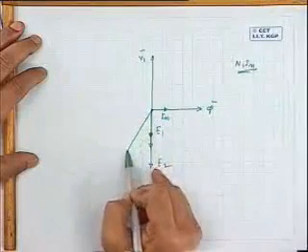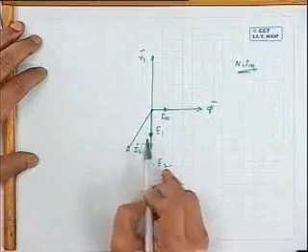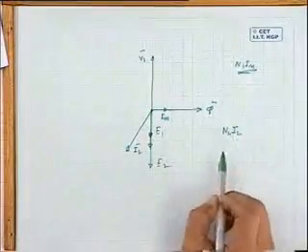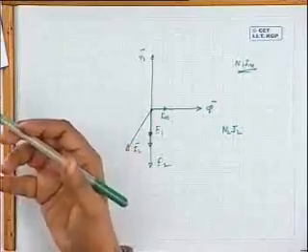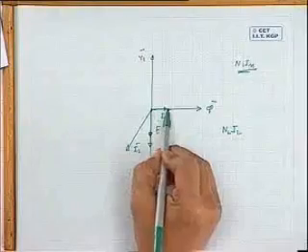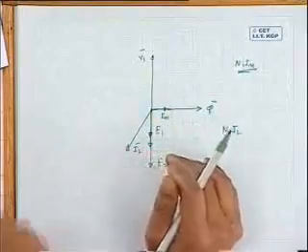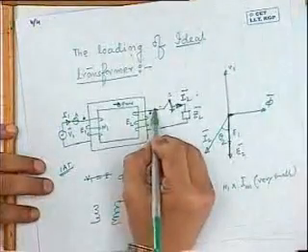N1 into Im. Now this is I2, the secondary current, suppose I2. So what is the secondary MMF? N2 I2. So the primary should draw now extra current to balance it out, such that on top of Im it will draw extra current.